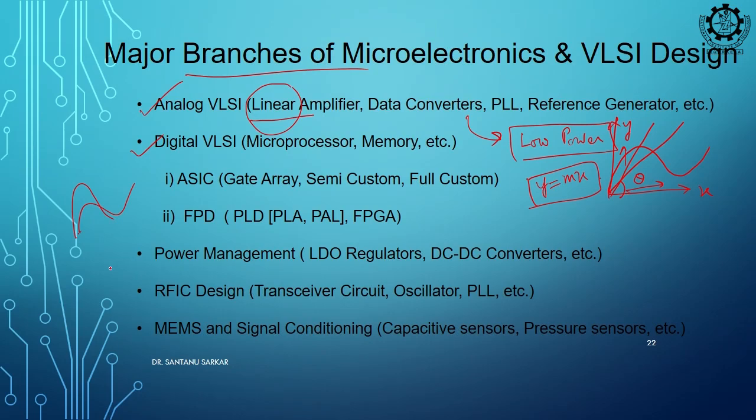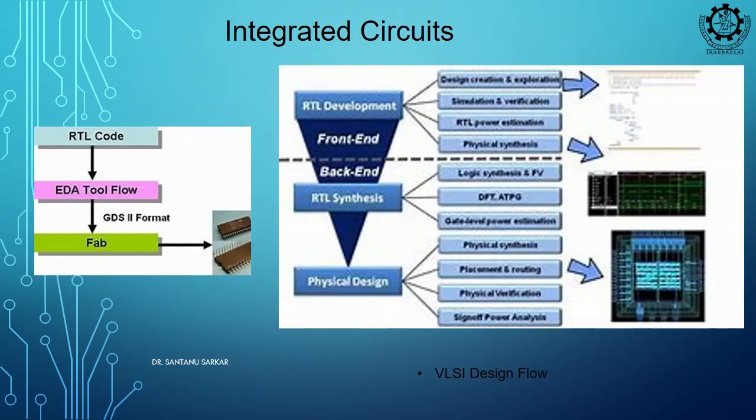In digital design, I do not need this. You see, you have an inverter, you give 0, you get a 1. So, it is getting saturated, right, it is going to the max. If you recall the inverter, this is the VTC of the inverter, right. Input is 0, output is 1, input is 1, output is 0, right.